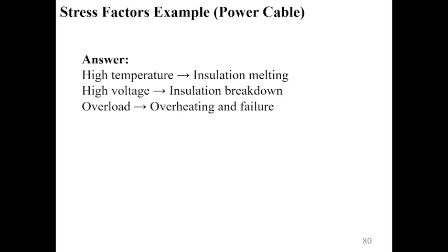Similarly, excessive voltage can cause dielectric breakdown in electrical cables, which is a common failure mechanism in electrical systems. In addition, overloading increases current flow, leading to overheating and eventual failure. This example clearly shows how environmental and operational stress directly influence system reliability. I just want to add this one to show the stress factors.